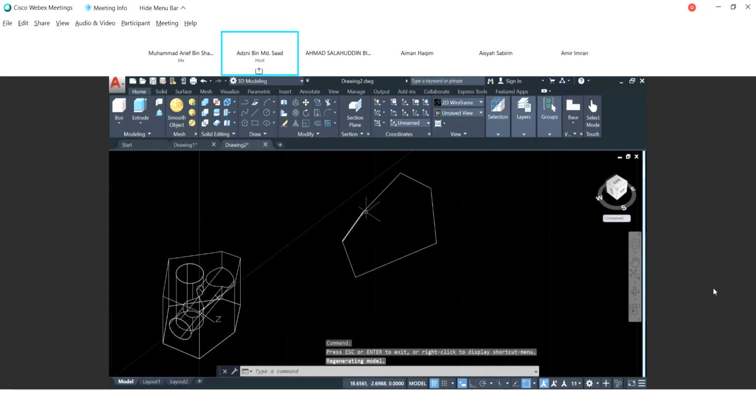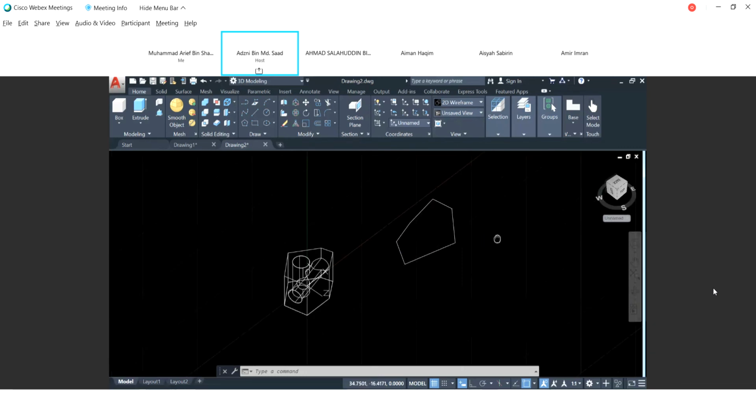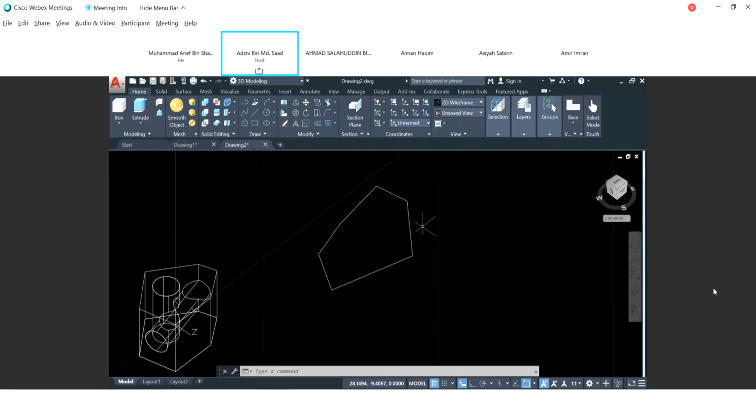Right now, what you're creating are individual lines, right? When your drawing becomes very complex later on because you have all the paths and all the lines, make it a habit to join all these lines to become one line, so that it's easier for you to use the press pull function and it can just detect one line instead of multiple lines.